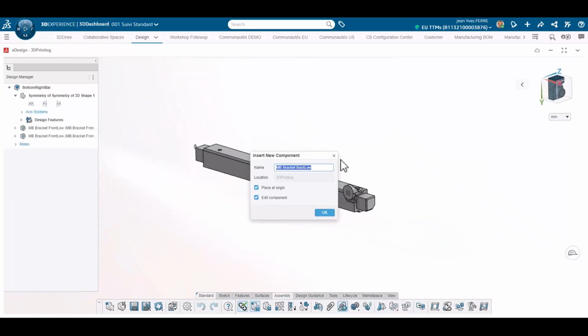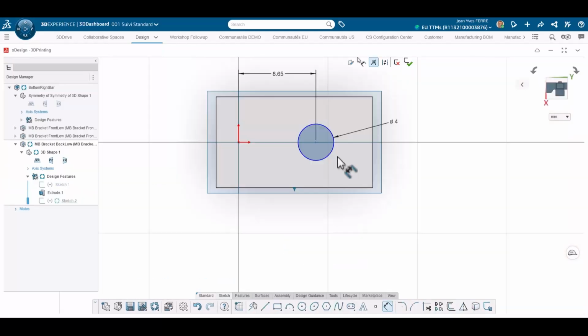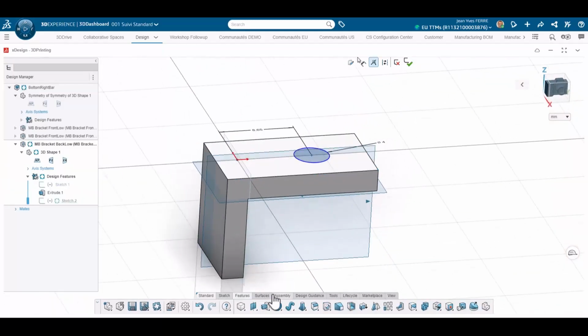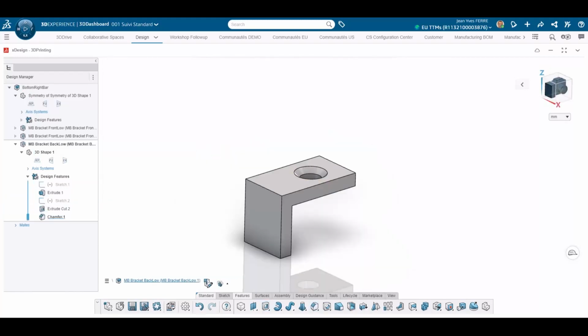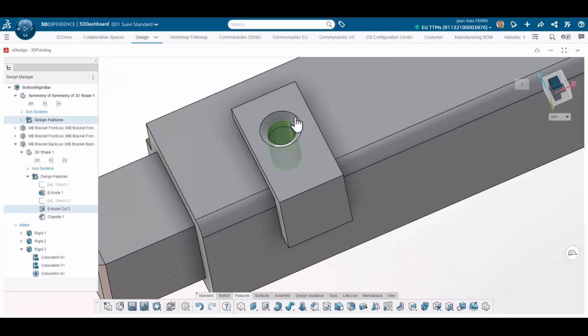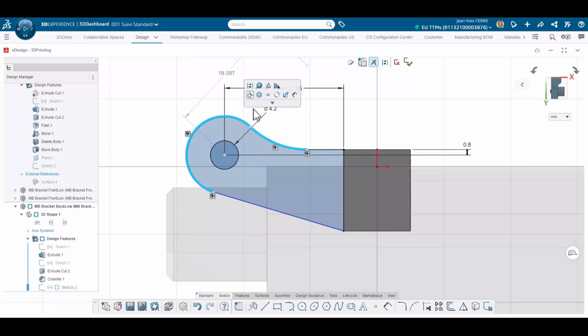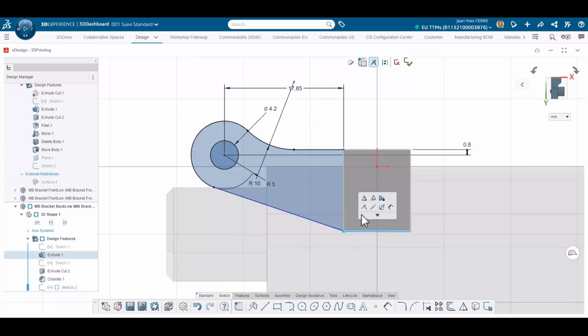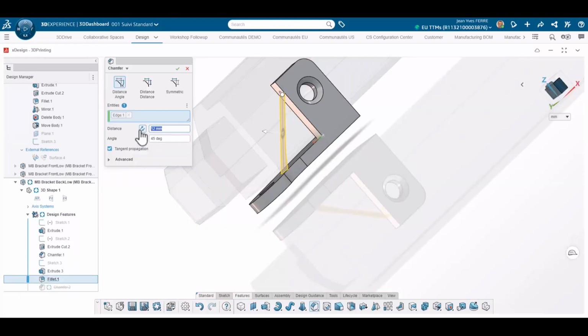Next one is tricky. It starts simple with a corner extrusion and a hole with a chamfer. So far so good. Once it's positioned correctly with mates, I start adding some material to link the extrusion to the mounting hole location. For that I create a sketch with a rounded boss, and link this boss with tangent arcs and lines. I add some fillets and see how fast and easy the shape is achieved.